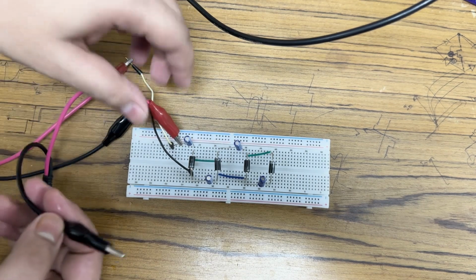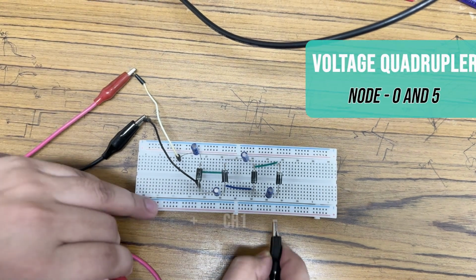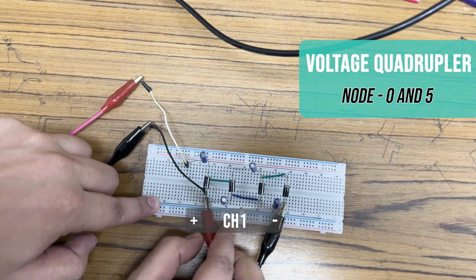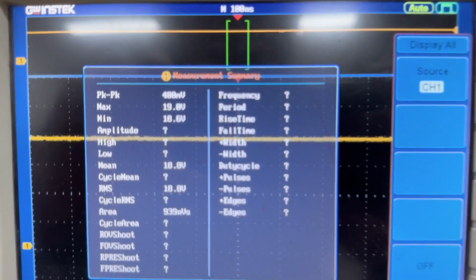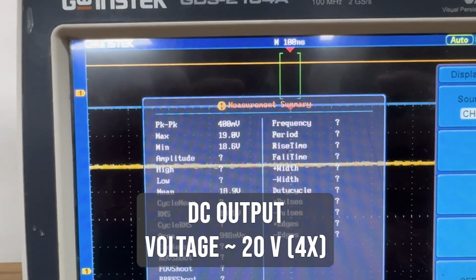Lastly, for the quadrupler circuit, the oscilloscope channel 1 was disconnected from the previous position and the channel 1 was now connected across the second and fourth capacitor from the input side. Again, the oscilloscope output window matches our expectations. The voltage is almost quadrupled and the output is also rectified.